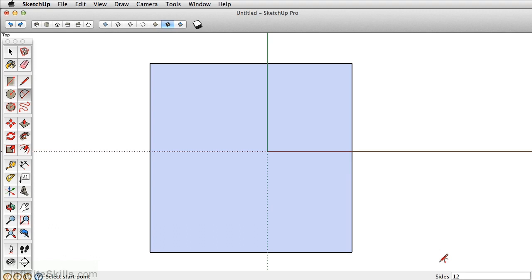Now what I want to do is create a perfect fillet, a round corner on this edge here. And I'm just going to start with an arbitrary point right here. So I'll click on the edge. It's my first click. My second click, I want to be on this edge. And you'll notice something as I hover down. You'll feel it snap. And it's snapping with that purple or magenta color. That's telling me that those two angles are 45 degrees each, giving us a perfect fillet. So I can click, set my endpoint, and then my third click is going to actually determine the radius. So in this case, I could type in the value manually, or I can hover until I see the magenta color again, letting me know that this is tangent to the edge. In that case, I'll click again to give our perfect edge.